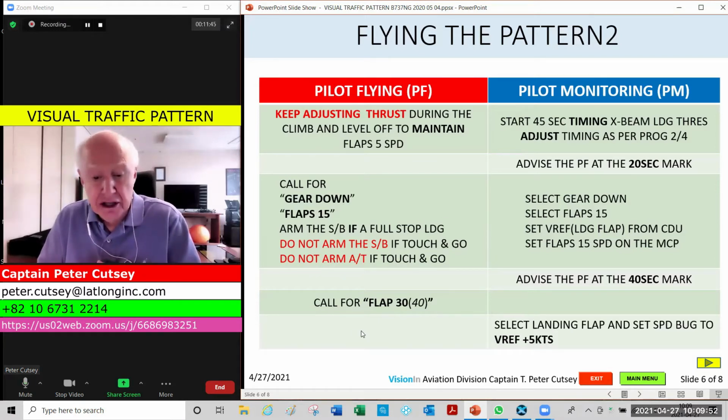As far as the timing is concerned, downwind the timing is broken down into 3 different parts. 45 seconds broken down into 20 seconds, 20 seconds, and 5 seconds. I'm talking nil wind. One of you or both of you should have prog 2.4 or 2.5 depending on your FMC update. That is where you can see the crosswind, tailwinds, etc. And you would make adjustments in the real world for headwind, tailwind by using half the headwind or tailwind and applying it accordingly to those defaulted 0 wind times of 20, 20, and 5 seconds. All right. So let's go to the next page.